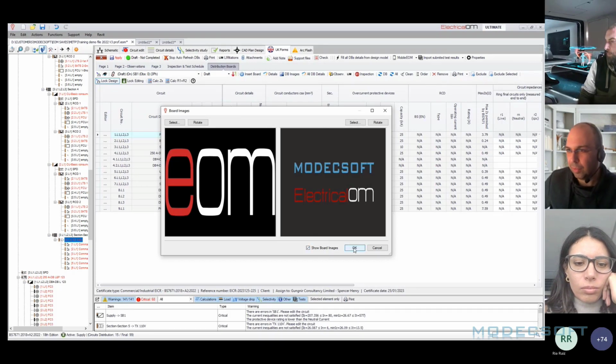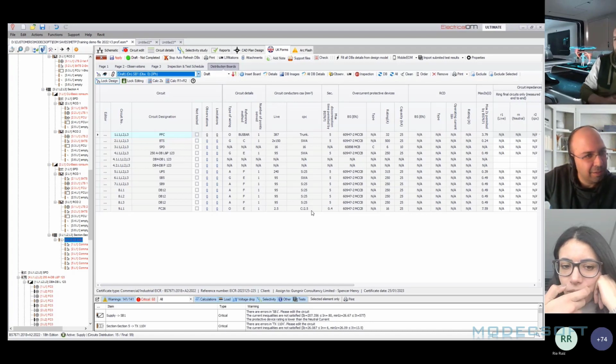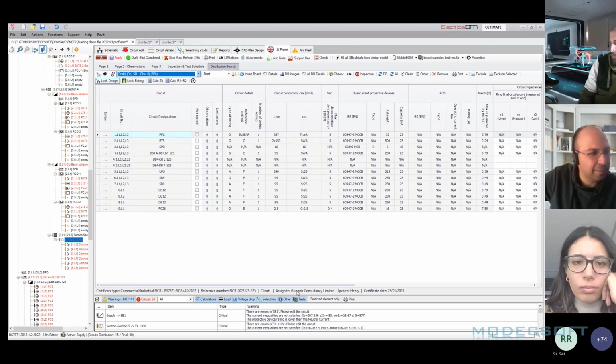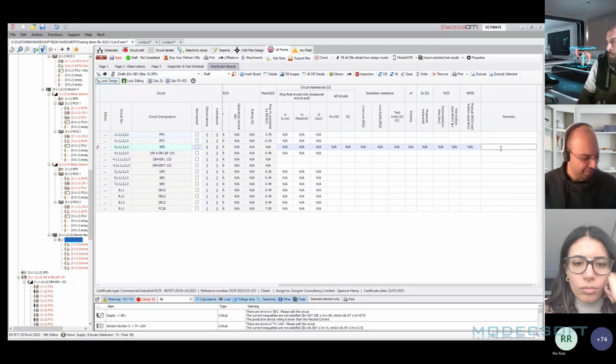Okay, I think Mick is asking a question. Can you record earth leakage current on EICR? I guess the answer is no. Well, yeah, no and yes. You can record it, but you would have to record it in the remarks column. There's not a specific column for recording earth leakage.